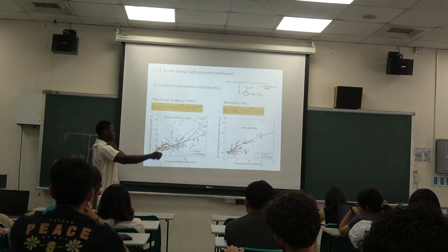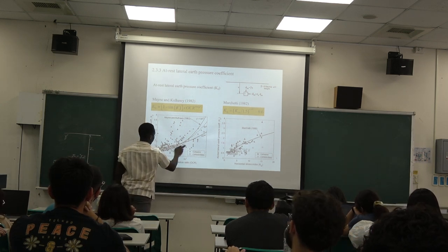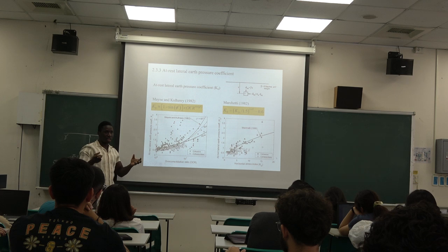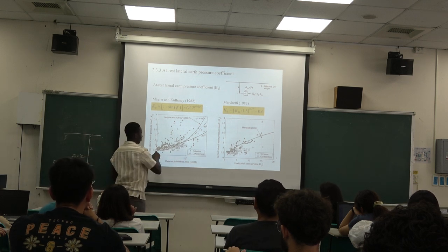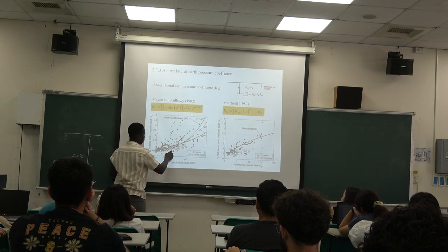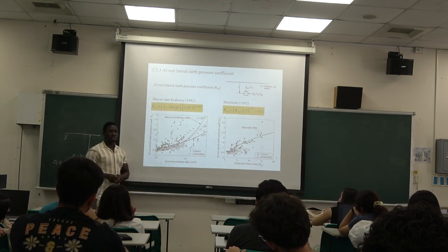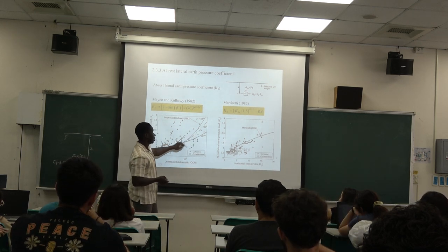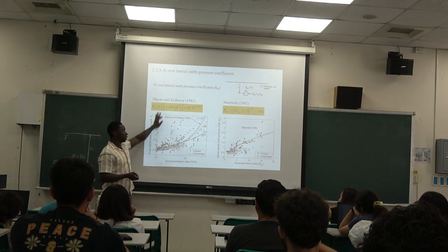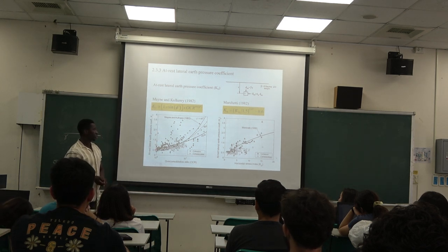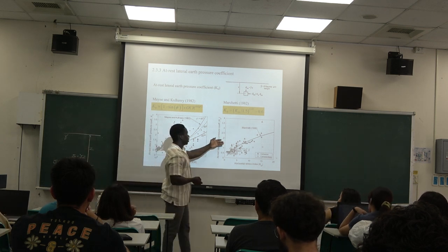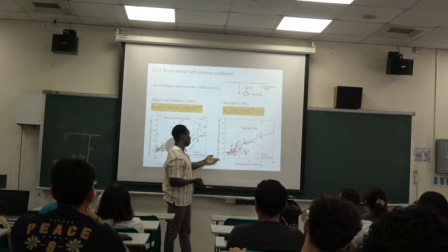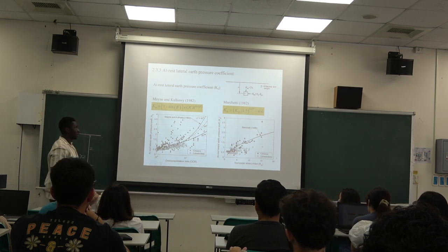So here you can see the same thing. They did a lot of experiments. This is for cohesive soils like clay and silt. They have cohesion. This represents the triangles, so you have a lot of them here. And this one represents the cohesionless soils, like sandy soil. They plot all of this and then try to draw a line of best fit, and the line of best fit is what gives this equation. And then this other study came up with this other representation. They used the horizontal stress index to determine the at-rest earth pressure, that is the K0 value.